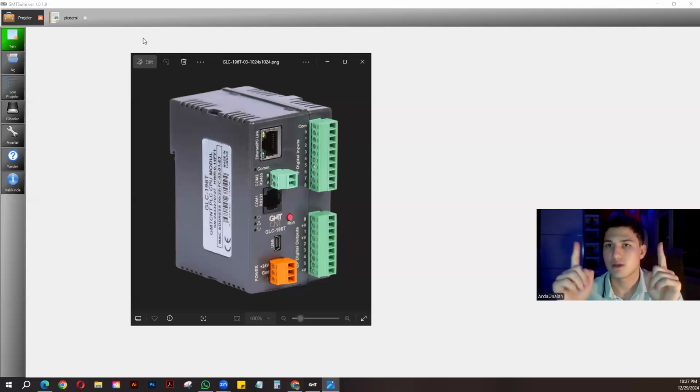Think of it like we got two tips of it. We just want to take one tip and plug it into our computer, and the other tip of the Ethernet, we just plug it into, you can see, this Ethernet PC link socket. By connecting them and making the right steps, we will be able to upload our code from our computer to the PLC. So this Ethernet port does that job.